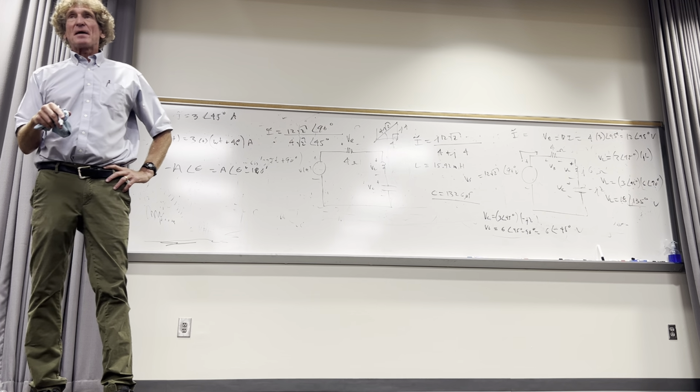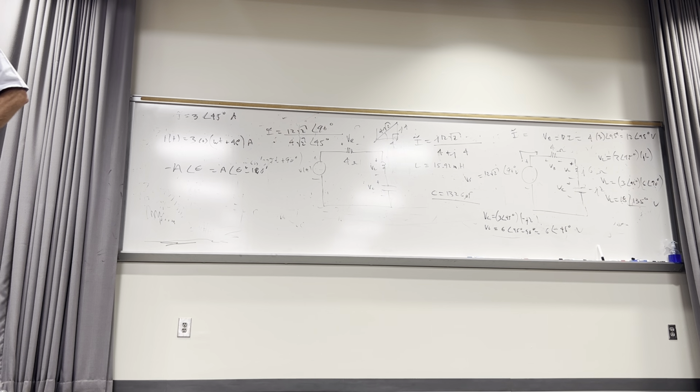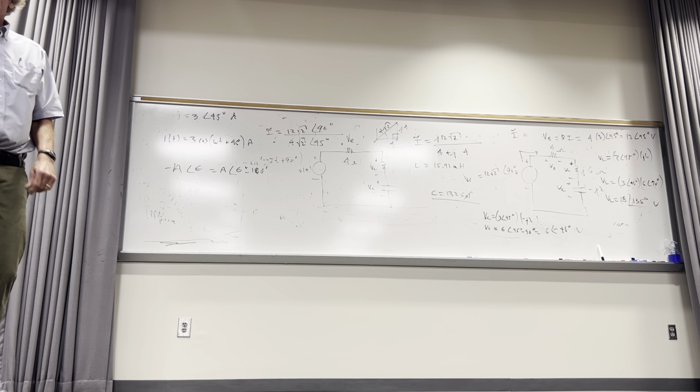All right, now the reason I'm asking for it in polar is that if you have it in polar, you can easily go to the time domain. The magnitude just carries over, then you have the cosine of omega t, and you add the angle. And you're back in the time domain, the observable domain. So that's the reason I do this. And by the way, a lot of times people have a natural animosity to doing that. Don't. The observable domain is the time domain. If we measure stuff, we measure it in the time domain. It's the way it is.